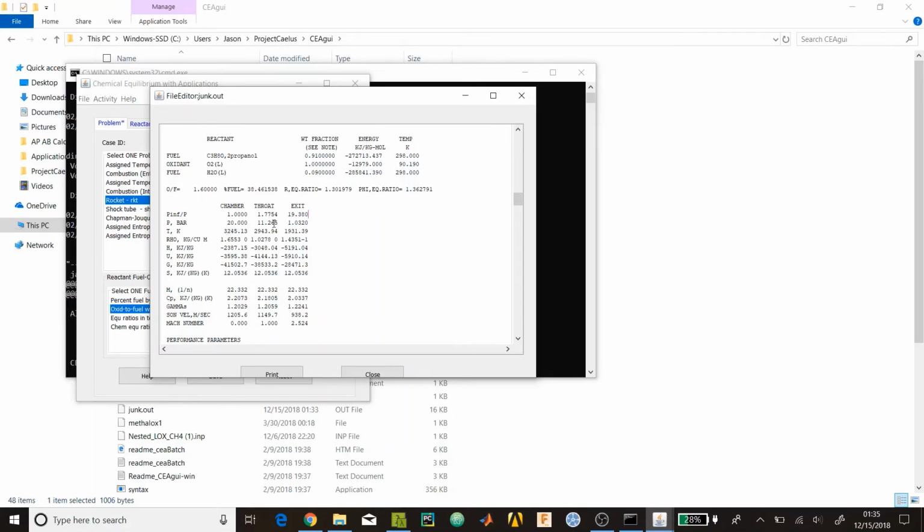But the downside, of course, is you want your nozzle and your chamber to be optimally shaped. So if the shape is constantly changing because you have graphite, then you can't use it more than once because the geometry is just worn away.